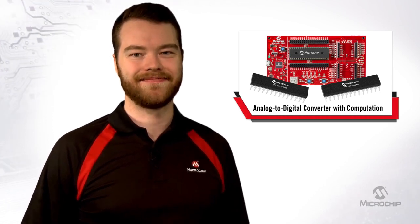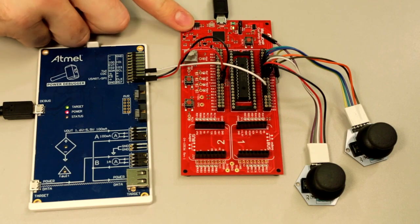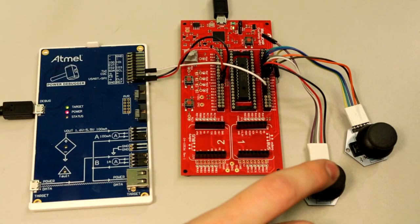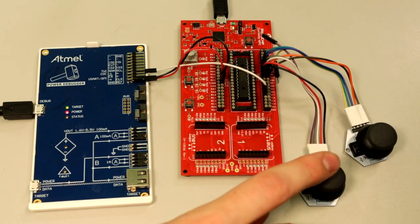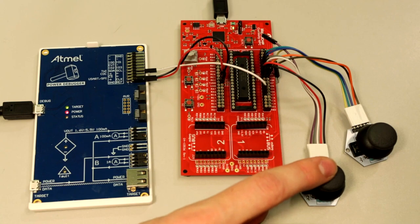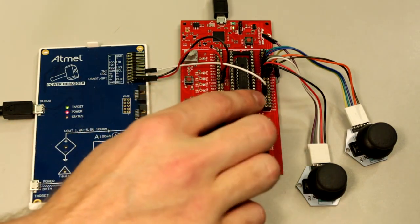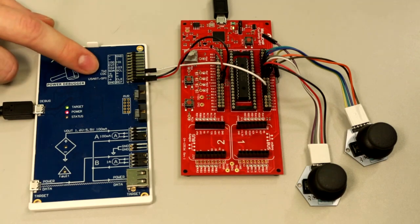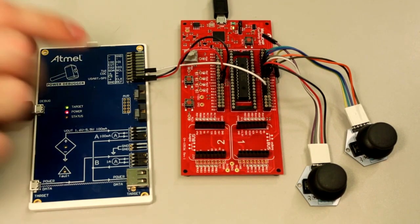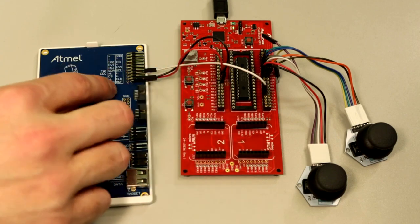So let's get started. Alright, so we have our Curiosity HPC development board set up again, and this time we'll be using these joysticks as our analog sensors. Now these joysticks have two axes, so we need to read both of those, and in total we will be using 4 analog channels. So we also connected the TX port from the EUSART on the device over to the CDC virtual COM port on the Power Debugger. And then we also have some voltage and ground reference going into VCC, GND, and REF.